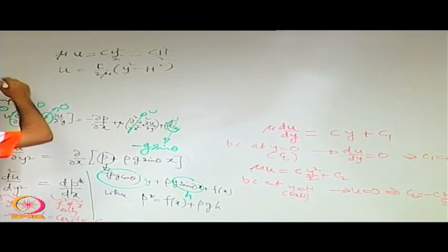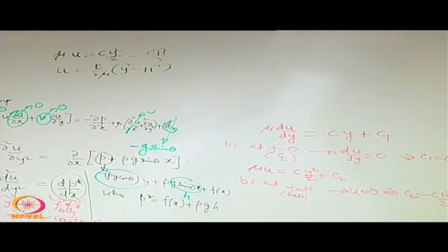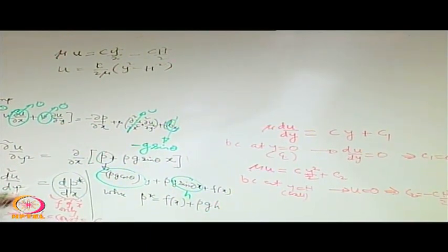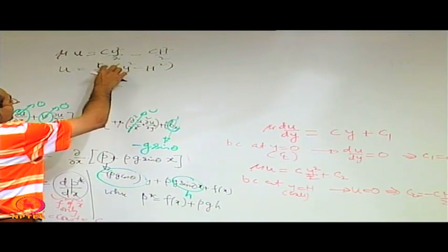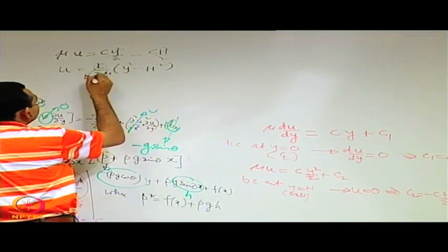That means c must be negative, and that is what we have seen, that you must have a negative gradient of the piezometric pressure. It should be from higher piezometric pressure to lower piezometric pressure, and so this dp star/dx, which is equal to c, is negative. So you know it in terms of the pressure gradient, and so this c is equal to dp star/dx.